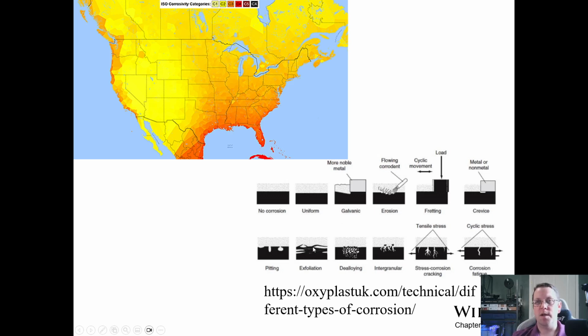So you see a lot of exfoliation type corrosion when rust forms in mild steels, so something that's uncoating. See a lot of this where you see flakes and layers of flakes, but they're always stratified like this. Dealloying can be selectively pulling elements out. So acids might only solubilize one of the components of the alloy, making it very weak. So it can sort of resemble pitting, but on a smaller scale. So it's a little bit different. And then intergranular can happen as well.